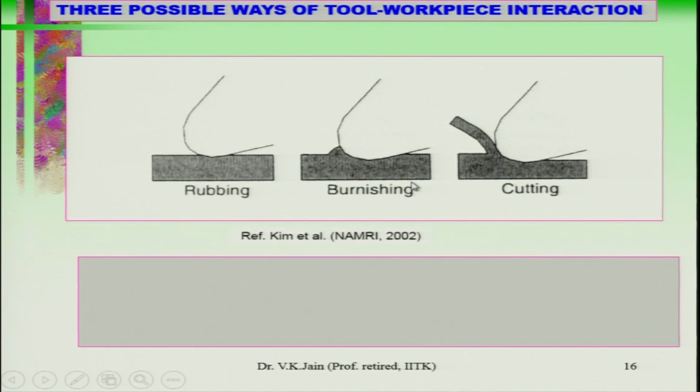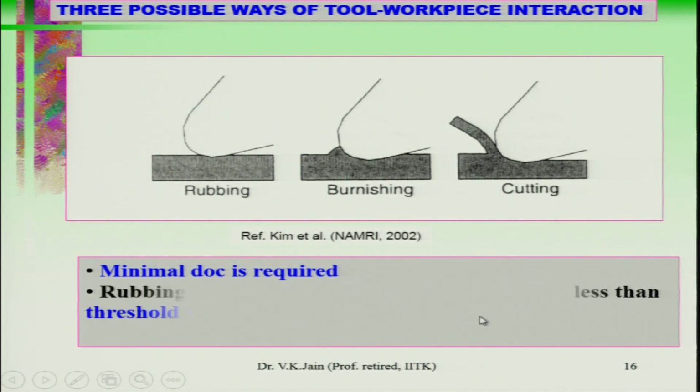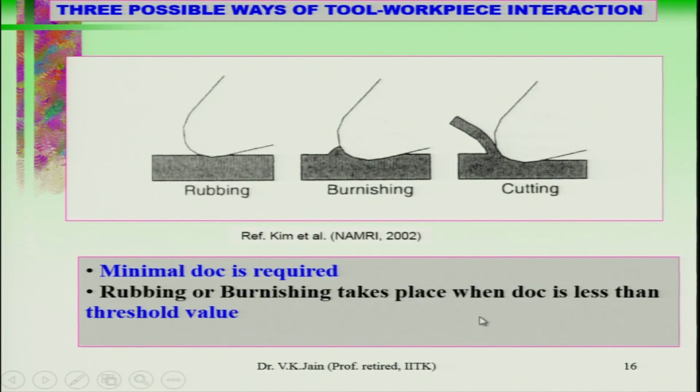So, you can have three cases: rubbing, burnishing and cutting. Mostly we are interested in cutting, not in rubbing and burnishing in general. So, a minimum depth of cut is required for the purpose of cutting.